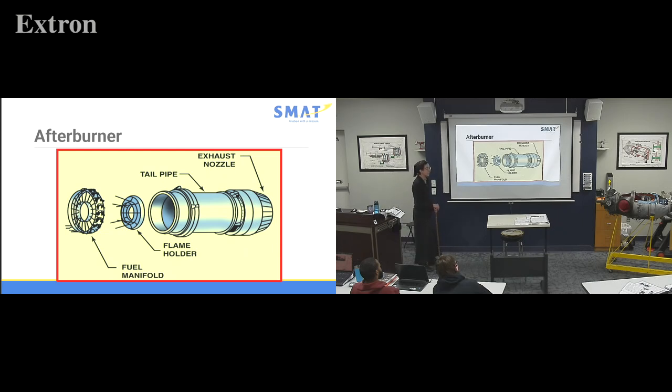So is that basically just another, like a second combustion chamber? Kind of. I mean, it's hot enough where we get more fuel, it ignites, but it's not considered a combustion chamber. Even though we're burning leftover fuel and more. Is that unburnt fuel at that point, or am I mistaken? So there is unburnt fuel, yes, and we also can add fuel. So it's both of those. And that would depend on the engine, like if we just want a little bit, we won't be dumping as much fuel, but on the military aircraft that I've worked on, they can.